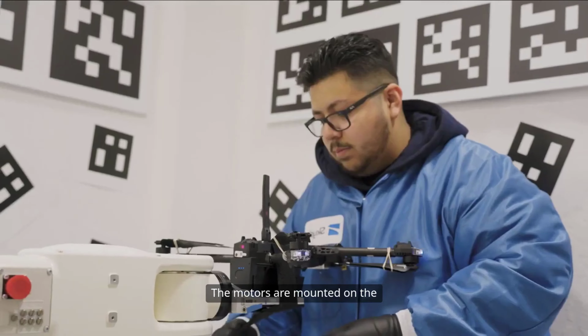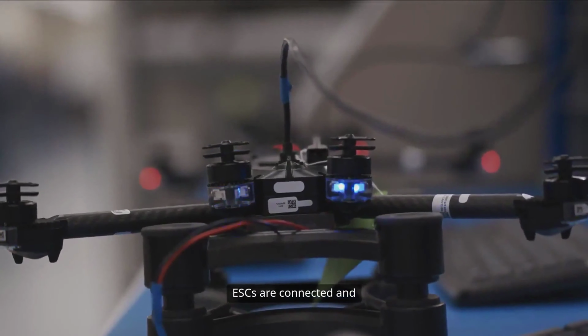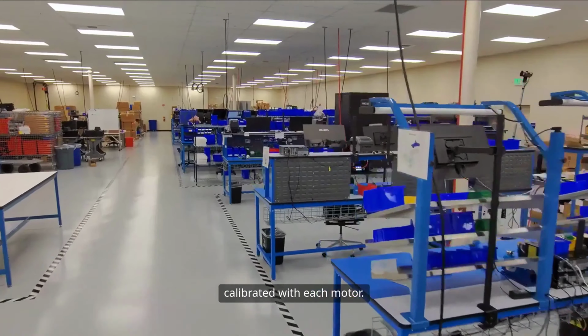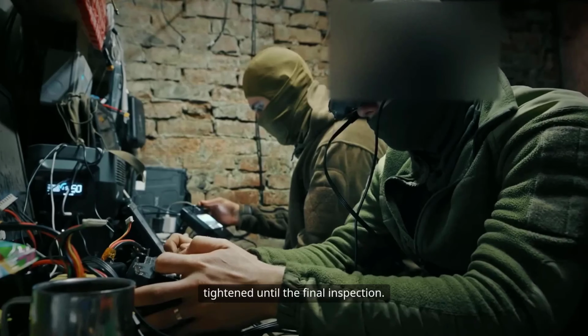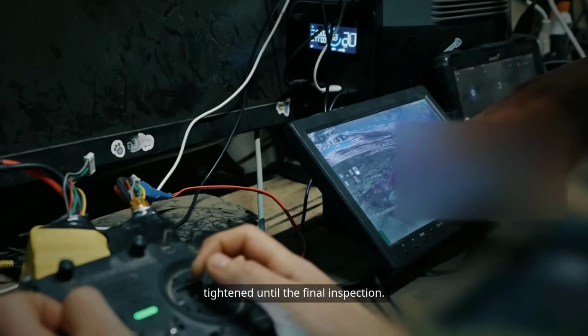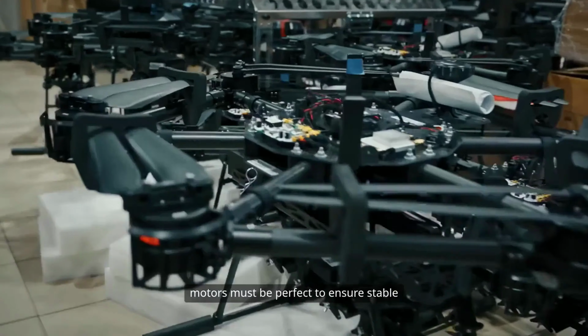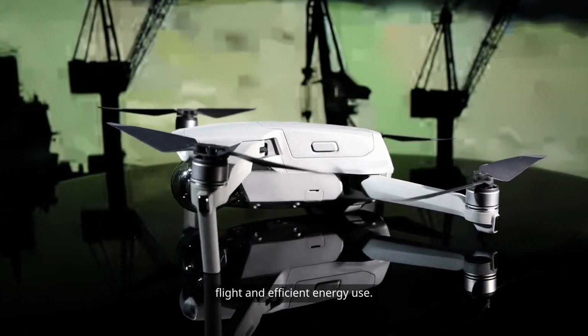The motors are mounted on the frame arms using precise mounts. ESCs are connected and calibrated with each motor. The propellers are installed but not tightened until the final inspection. The alignment and securing of the motors must be perfect to ensure stable flight and efficient energy use.